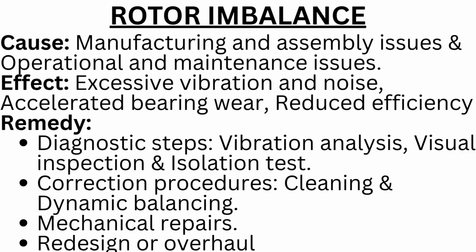The next mechanical failure that we will look at is rotor imbalance. Cause: manufacturing and assembly issues and operational and maintenance issues. Effect: excessive vibration and noise, accelerated bearing wear, reduced efficiency. Remedy: diagnostic steps, vibration analysis, visual inspection and isolation test. Correction procedures, cleaning and dynamic balancing. Mechanical repairs, redesign or overhaul.